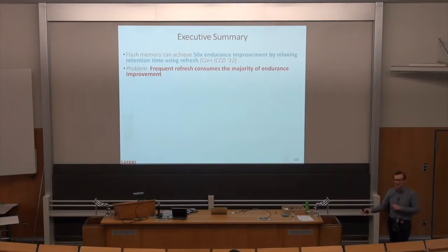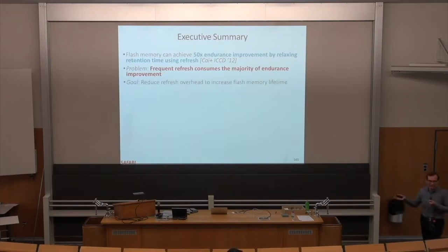And that actually gets rid of some of your endurance improvement, because when you remap, you're doing program and erase cycles. Right? So you put in refresh to improve your program and erase cycles, but you're taking away from some of your program and erase cycles because of refresh. So these work against each other. So how do we reduce the refresh overhead? Reducing the refresh overhead becomes important here, especially toward the end of your lifetime in flash memory. And lifetime is going to be even more important going into the future, especially as we improve the capacities.